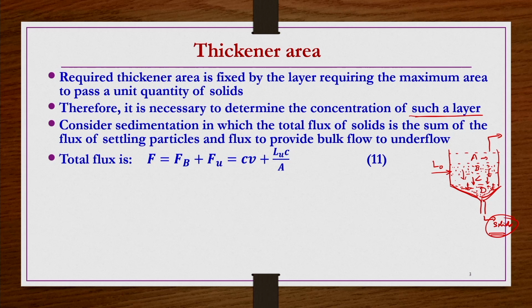Okay. If you are obtaining the flux at theta equal to 2, because now the solids are continuously settling until a final total or almost complete sedimentation takes over. Until that point, solids are continuously settling, and at each layer, at different times, the solid fluxes are different, right. So, this solid flux, if you calculate at different times, then you can have F versus concentration information, because the concentration of this layer is also changing with time, right.